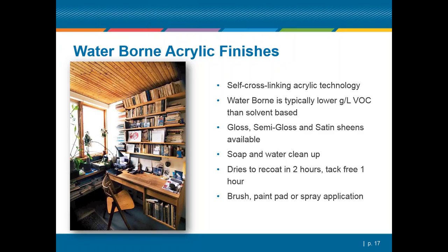The biggest reason for that is we don't want to roll any air into these finishes. Whenever you're talking about a roller, even a very, very thin nap roller, the propensity is to roll air into that finish. That air has to come back out, and that air entrapment will create little fissures and a pattern like an orange peel effect on the surface, which is normally not very much appreciated when it comes to wood finishes.